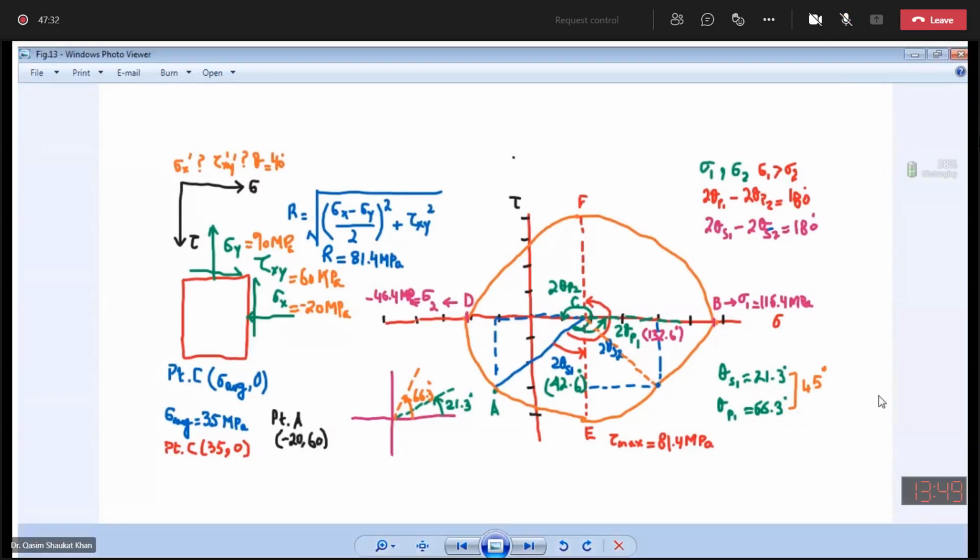Okay, so if you have any question about the Mohr circle, you can ask me. In this example, I used the data 9.8, but I have covered all 9.7 and the other examples because I have asked you to calculate the principal stresses, orientation of the principal planes, maximum in-plane shear stresses, orientation of the shear planes. Then I have asked you to calculate transformed normal and shear stresses of the point or an element which is oriented at 40 degrees counterclockwise.